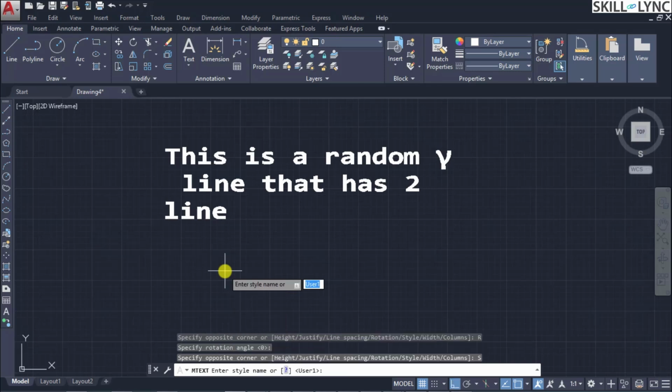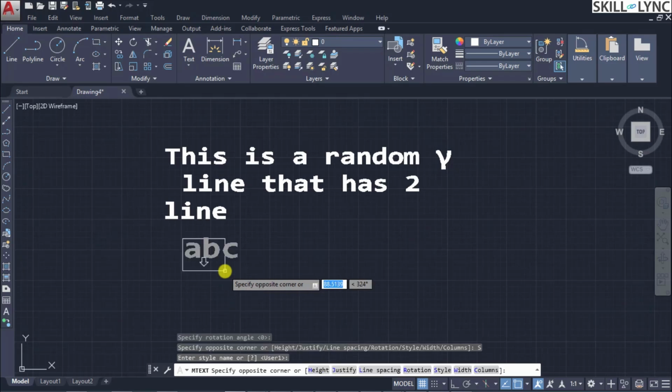So earlier in a single line, you had to either select the styling earlier or update it individually for each and every object, but here you have the selection to use within the command itself. So here, if you click on the down arrow, you can select the different styles that are available. Right now the style we have selected is the user one, so you can select with that. Suppose if you want to change the styling also, you can do it once you have gone into the multi-text editing properties.